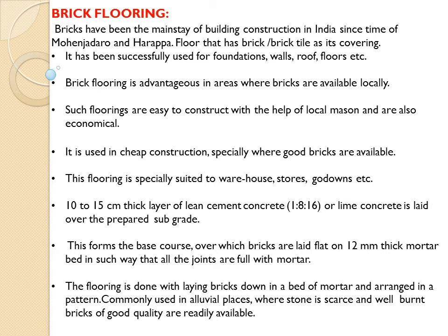By giving a proper level, by flattening the surface using the cement mortar, a level is done. For that the brick is added. It can be any, not only brick. If you are going for stone flooring, even the stones can be added. In case you are going for tile flooring, a mortar bed is mandatorily laid. The flooring is done by laying bricks down in the bed of mortar and arranging them in a pattern.